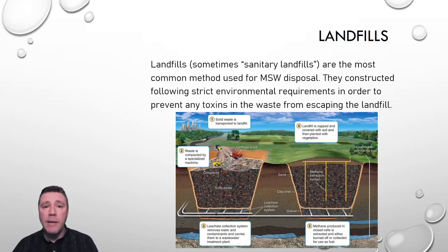A system of pipes is constructed below the landfill to collect leachate, which is the moisture that is compressed out of the waste being buried. The leachate is tested regularly for toxicity. If it exceeds toxicity standards set by regulations, landfill operators are required to collect it and treat it as a toxic waste. Once full, a landfill is closed and capped off.